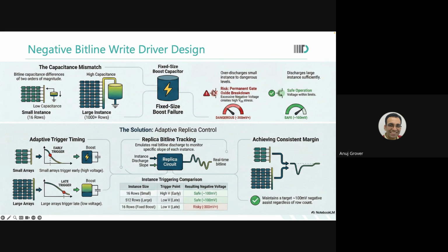Okay, you tell me, in the example we just saw, when I had kept the bitline charged to 0.6, even after putting the negative word line driver, my final voltage was coming to be zero. Was it not? That was what we saw.